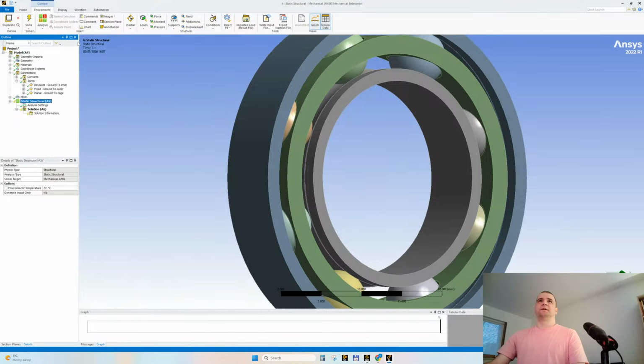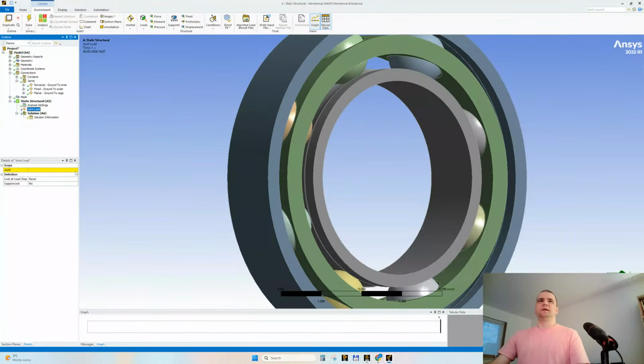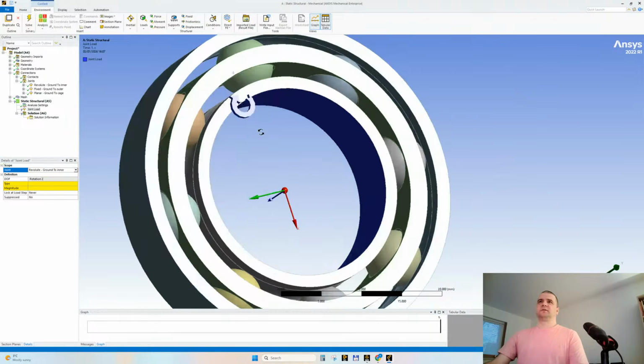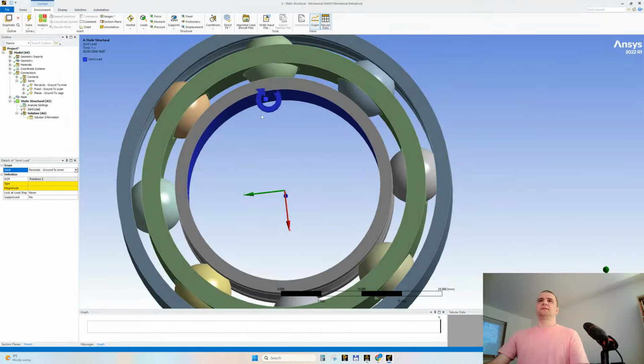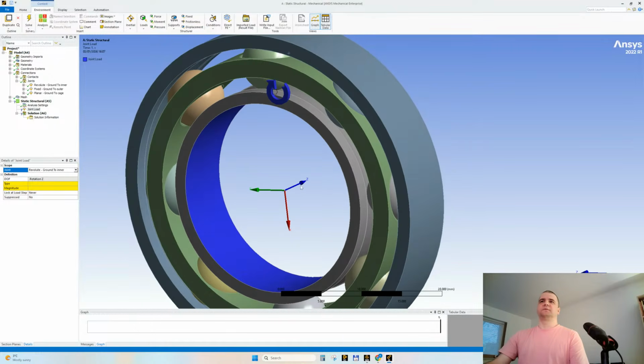Let's now go for the loads, and you will see in a few seconds what I'm talking about. Joint load. The only load that appears at this moment in this simple tutorial is this rotation. Yeah. Why does it want to put it here instead of here? We don't care too much. Yes, it's just a detail. But we know it rotates about this z-axis.